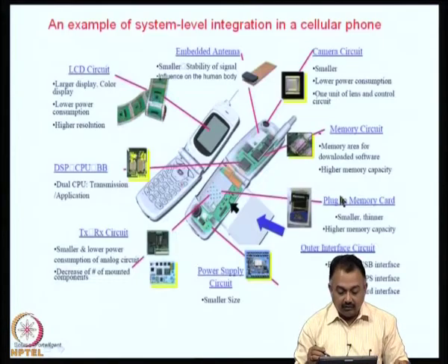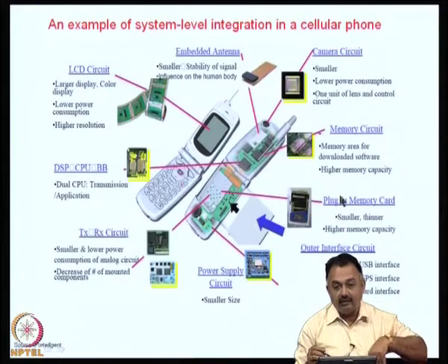Now, when you use a cell phone or a mobile phone, the very common thing is dropping it. Many of us have dropped the cell phone a number of times, but the first thing that we check is whether it is working. So, mechanical reliability is also very important, because when you drop a device like this from 1 meter, there is a mechanical shock exhibited on the surface of the device, which is again propagated into the board, the components, the solder joints, the display and so on.